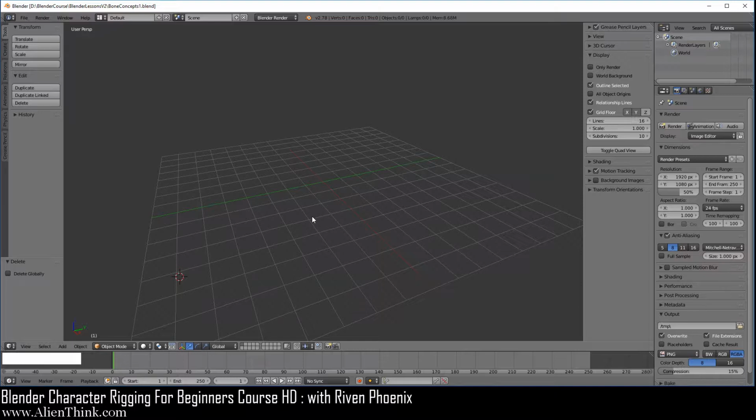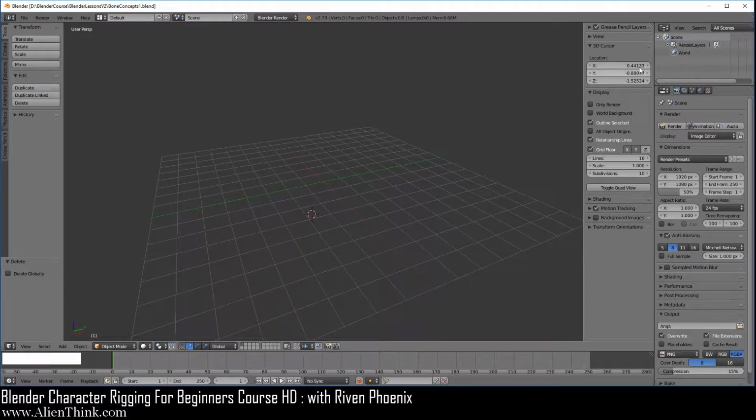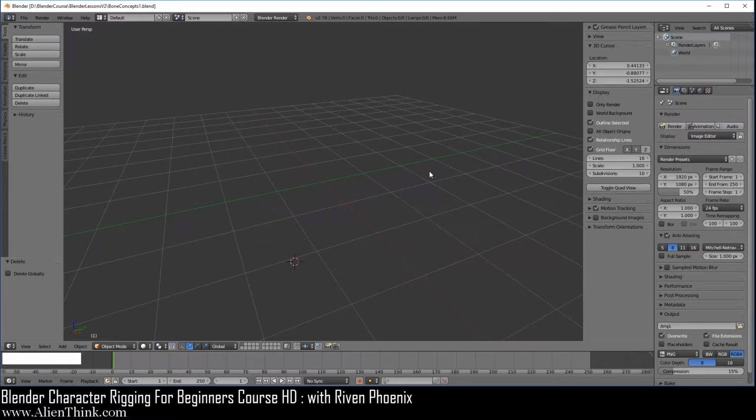So if you click your left mouse button to place the 3D cursor over here and open up the 3D cursor panel, you will notice that it's going to show you how far it is away from the center of the 3D grid. I'm going to go ahead and zoom in with the middle mouse button. When we do Shift C, the X, Y, Z should get zeroed out.